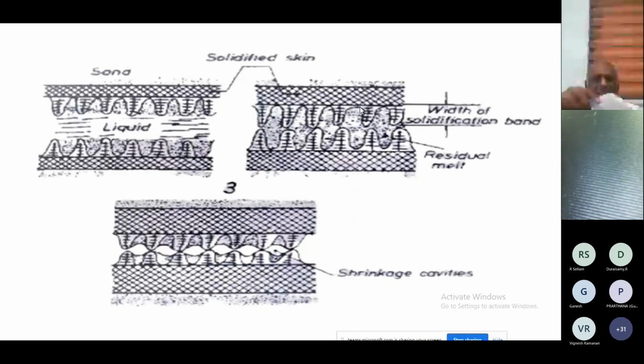Next is the three phases of solidification of a plate. A solid edge zone is formed with a broad liquid zone between advancing crystal fronts. Liquid metal flows freely and always remains in contact with dendrites, thus filling up the space. Secondly, the crystal peaks constrict the flow of metal and finally come into contact. Eventually, the flow of metal is cut off and sinkage cavities are formed.